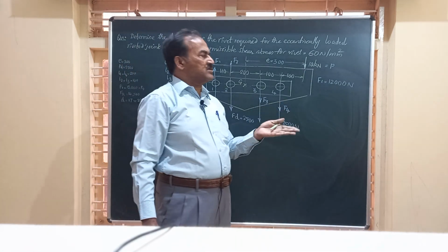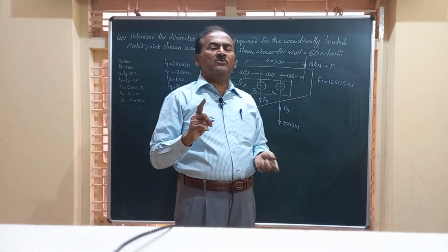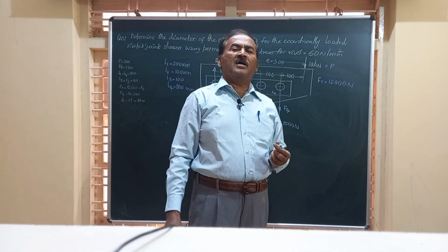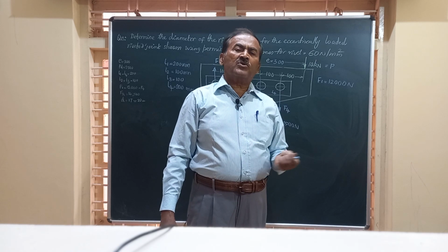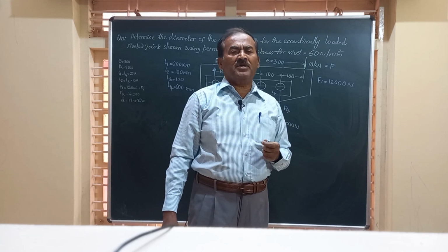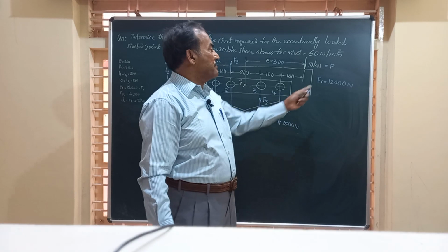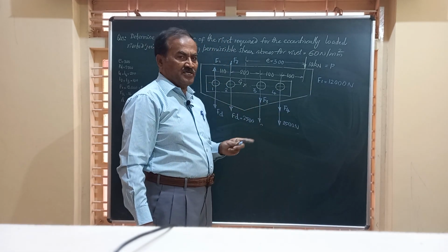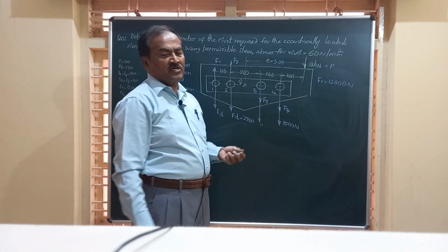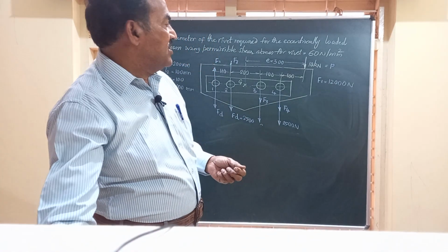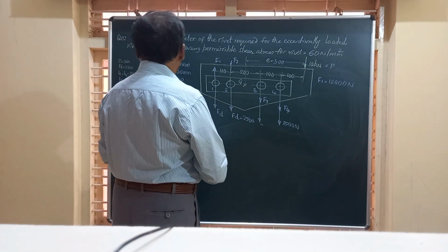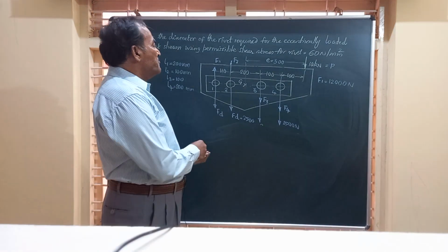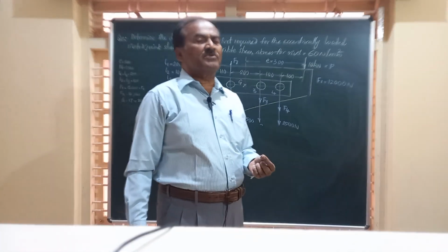And we can just say that the secondary loads act at the centers of rivets 1, 2, 3 and 4, so as to produce a similar moment as that produced by P about the centroid or center of gravity G. Friends, we have marked the direct load and the secondary load acting at each of these rivets. Next, friends, we have to identify, in step number 4,